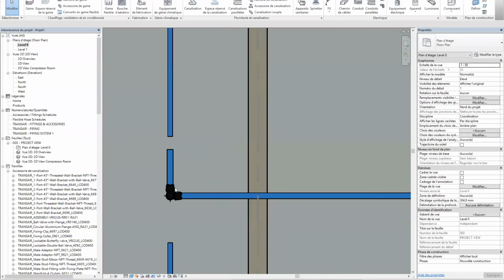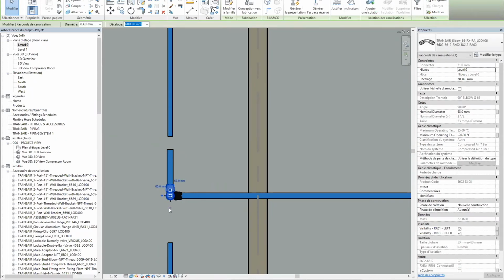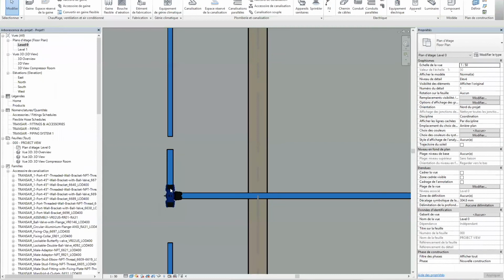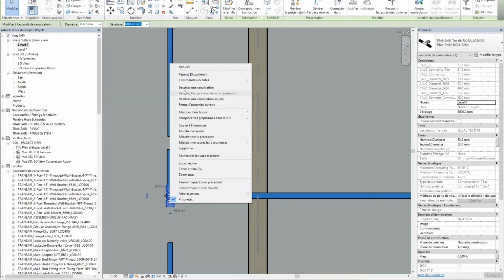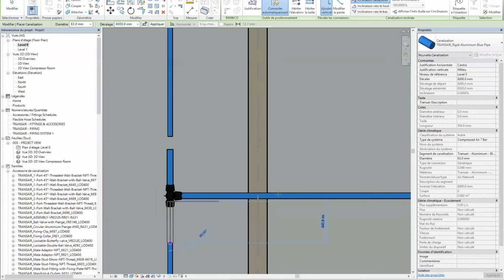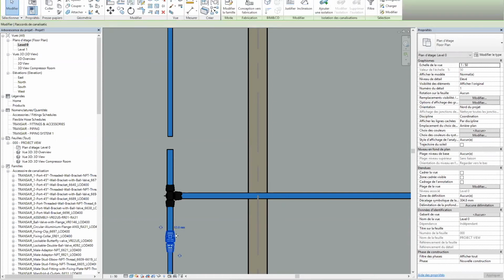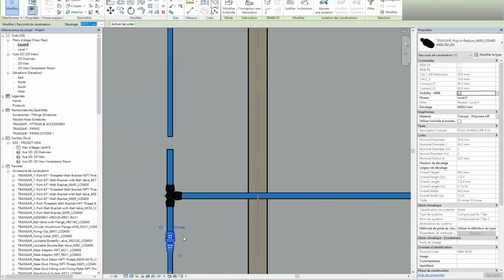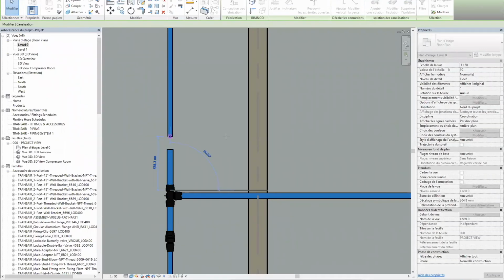Revit is creating an elbow. I'm going to press the little plus here in order to convert that elbow into a T. And there you have it. You just need to connect the piping diameter 63 to the piping diameter 50, and Revit is automatically going to add the plug-in reducer. And as you can see, the plug-in reducer has the right product code. The T here has the right product code, meaning it's good. Those objects do exist. And I do the same here.